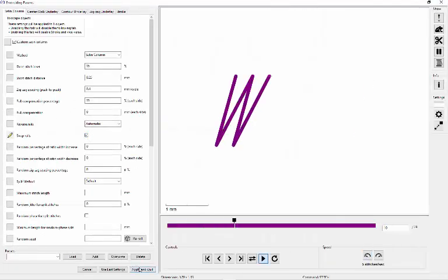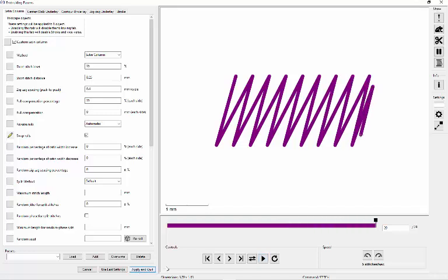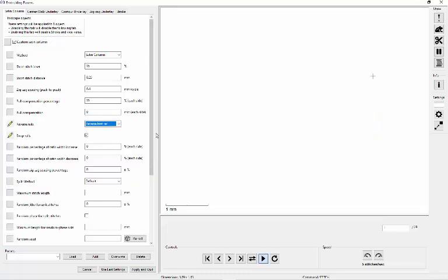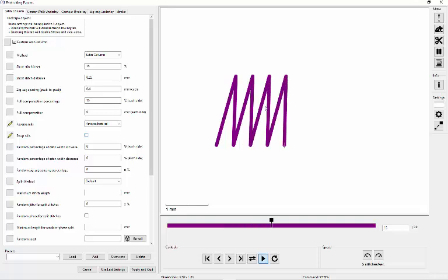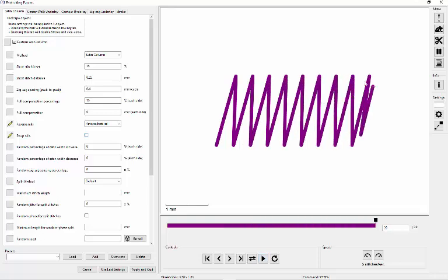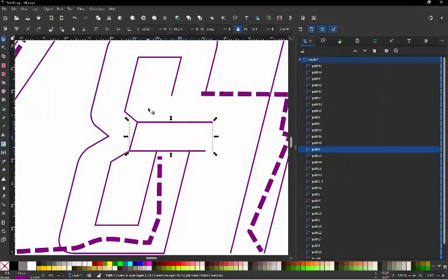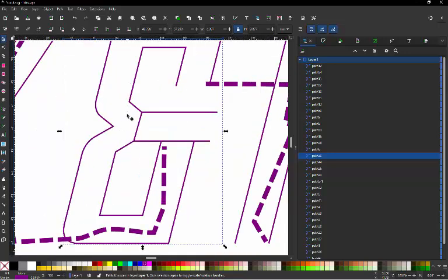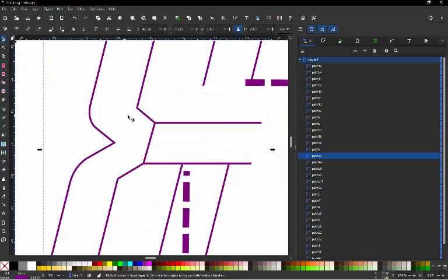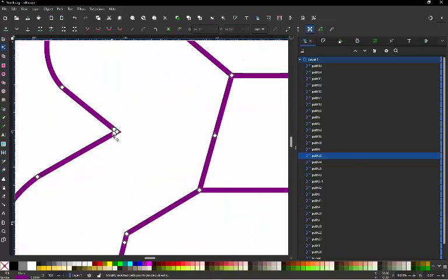So we'll go ahead and make sure it's stitching from left to right, and it's ending at the bottom. Let's go ahead and swap our first rail then, and not swap rails, and then it should stitch up top and up top, which it does. So that takes care of that. And then I want this to end somewhere. So I think what we're going to do is we'll just end it right here.